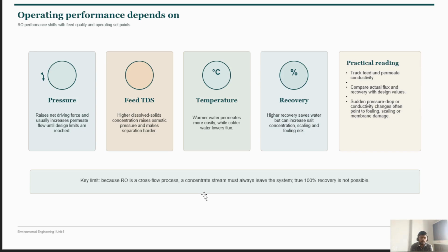The temperature also plays an important role. Many times you must have seen that high temperature may cause damage to the filter membrane, or change the flux, increase the flux. It depends on the temperature, but there is no treatment method where we can control the temperature. For a smaller unit it is possible, but for a larger unit temperature control may not be possible. Still, it is going to affect the working of the membrane process.